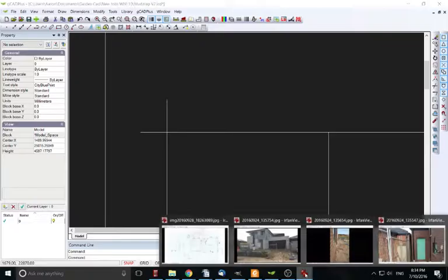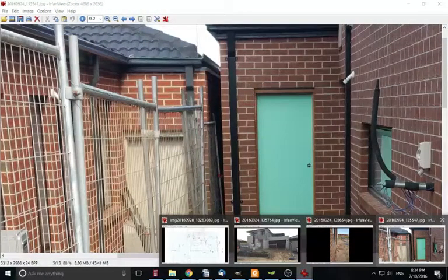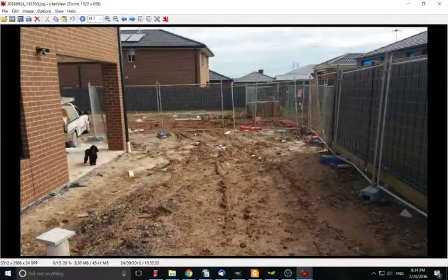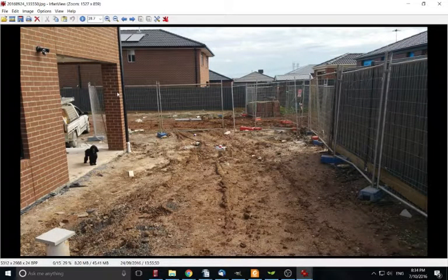So this pillar, let's have a look. We have the back of the house somewhere here. Wrong way. Okay, so that pillar there. Look at that, we've got 2 brick widths. Each of those bricks are 230 mil. So that's 460. Mortar gap's about 10 mil. So you've got about 470 pillar right around there. And it's good to know measurements of products in buildings, so you can do things like that quickly.